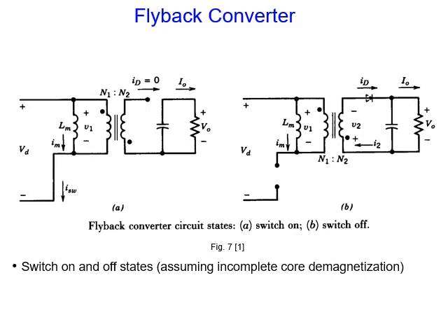As you can see, I represented the transformer here. This is the magnetizing inductance, this is the switch. When the switch is on, as you can see here, short circuit, current will flow here and back to the supply. Plus on the dot here means plus here, minus here. When minus here, the diode will be open circuit and it will not conduct to the winding. When we open the switch, the energy stored in the inductance will be released in this direction. So plus here, minus here. When minus here, then the current will flow here, because plus here will flow through the output.